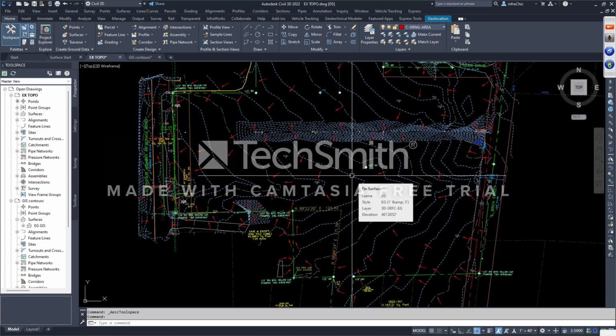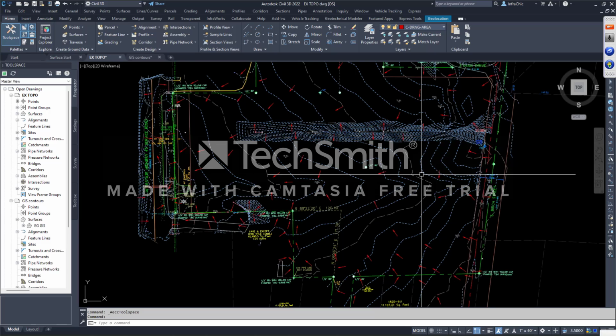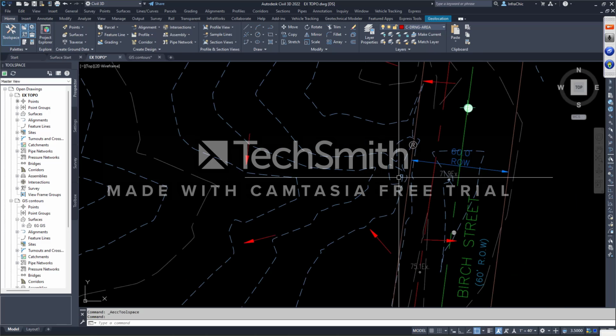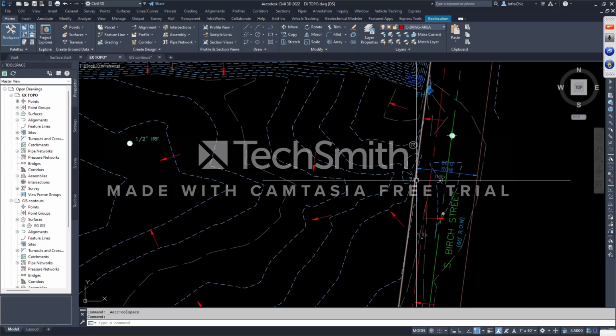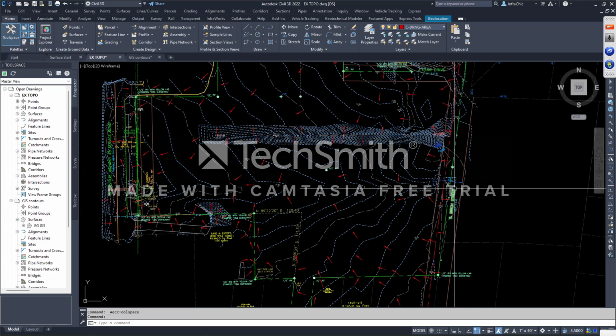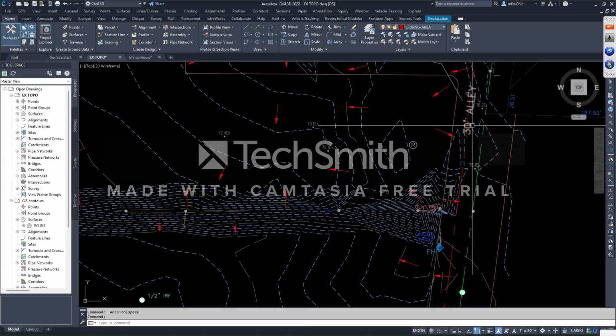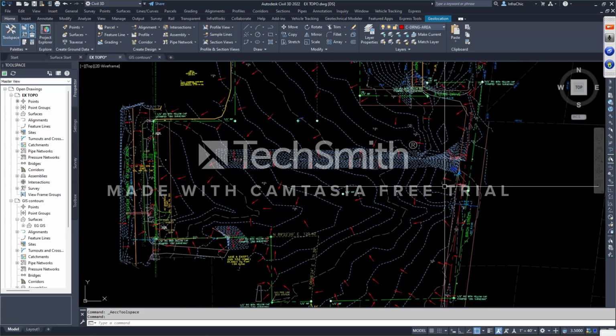You might want to ask the guys if they took any photos. Photos help. They tell you the world of things. They'll tell you if there's a low spot, like over here. Was there a catch basin in the photo that maybe they forgot to get? Happens all the time. Don't dock them. Just let them know it. You missed a point. Where's the catch basin for this low spot that's right there?